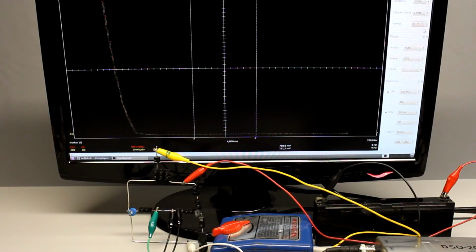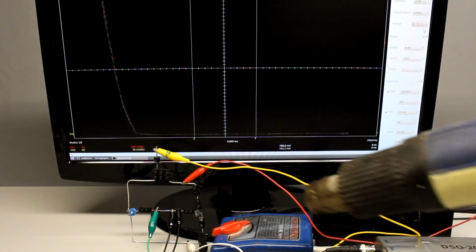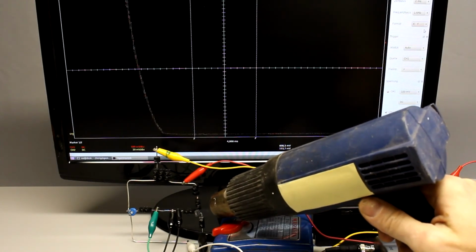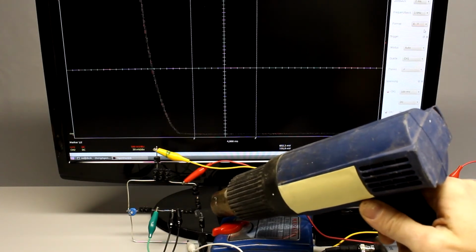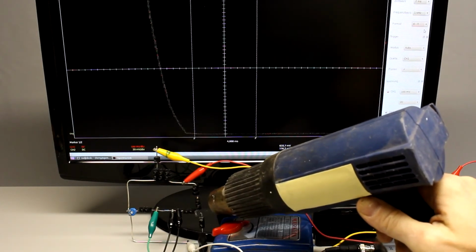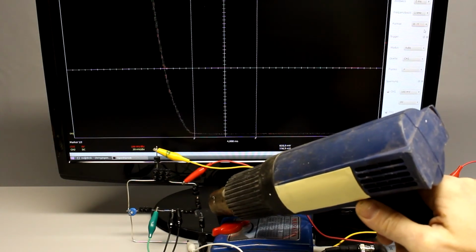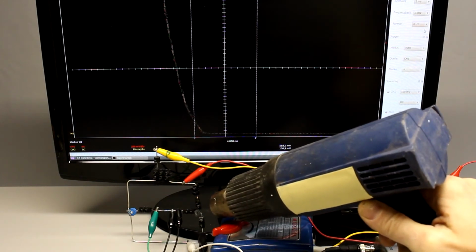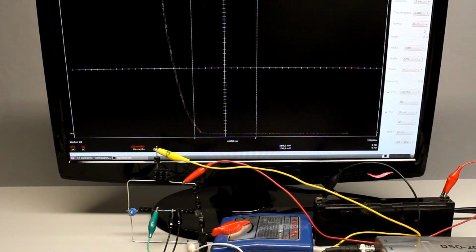of the x-axis. With the help of this arrangement, I would like to demonstrate the influence of temperature on the recorded values. The transistor is heated up by a fan heater, by which the curve is moving to the right. In comparison to the cold transistor, a clearly higher base current is running through the device if the base voltage is kept at a constant level. While cooling down, the curve is moving slowly to the left. So if you intend to do very precise measurements, you have to ensure that the temperature of the transistor is kept at a constant level.